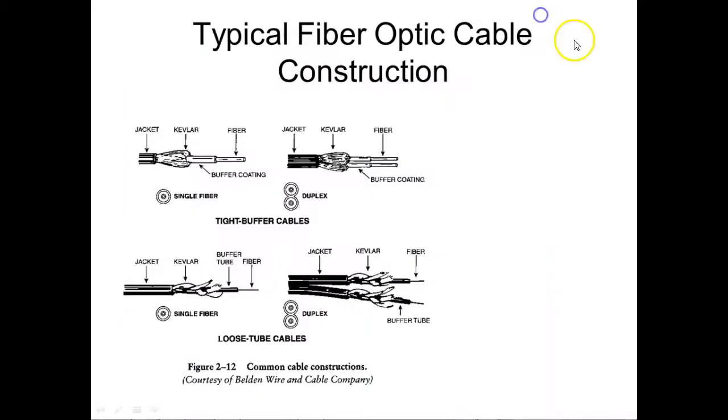Plastic is a little easier because we cut plastic and then we can sand it down to get a nice flush surface on it. Plastic is a lot cheaper, but it's got a lot more attenuation to it. But it's not designed to run over long distances, right? And now one big advantage of fiber, it is impervious to EMI. We can set off a nuclear blast or one of these big EMI pulses. It'll tear copper up, but fiber don't care. Oh yeah, we can run this through anything. We can run this through any environment.